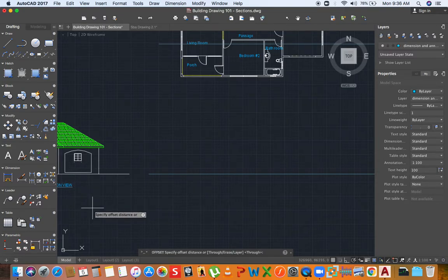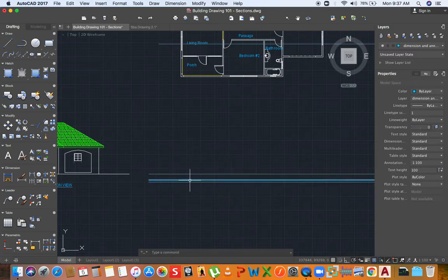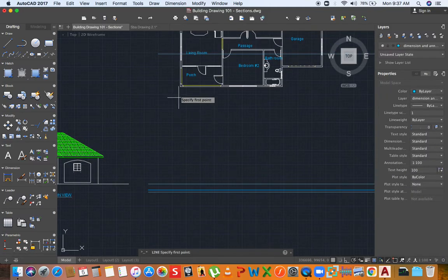I'm going to establish what we call the foundation level. In this case, 900 millimeters. That's how low the foundation will be. And the thickness of the foundation footing, 300. I'll put 250. So the foundation goes all the way to this level, and then the foundation footing before the walls are being laid will be 250. So these are the lines that I'll need. And in addition, I'll need a regular line, 300 millimeters from the ground level.